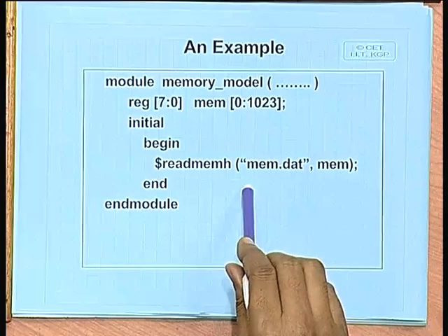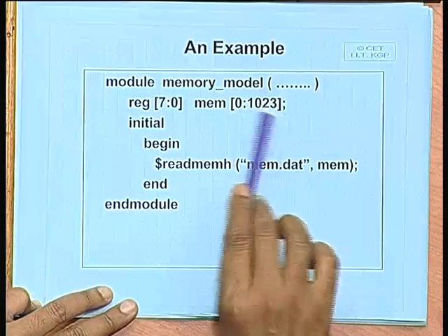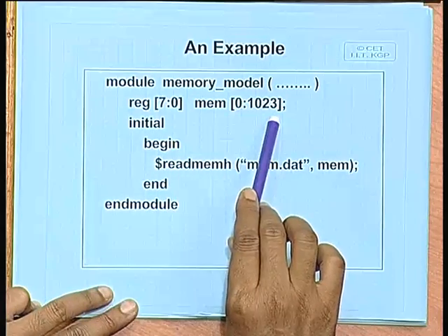This is not the instantiation of the module. Here I am defining the memory as a 2-dimensional array, as an array of registers. Is memory an instantiation of a specialized memory or just registers? When you say that I am instantiating a memory from the library, that is not a register array, that is the entire specialized memory designed and fabricated.